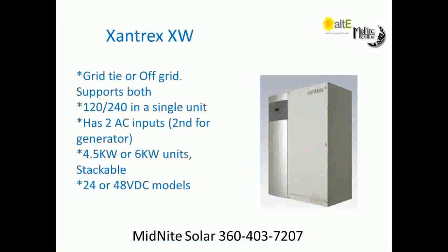And what it'll do is, as the batteries start to get full, something you've programmed in, say, okay, at 59 volts I want my batteries to be considered full, it will dither the frequency enough to actually kick the grid tie inverter offline and start charging the batteries. And when the batteries fall back down, it will bring the frequency back into spec and let the grid tie inverter connect back up and charge the batteries again. So that's completely automated, no intervention needed by you at all.